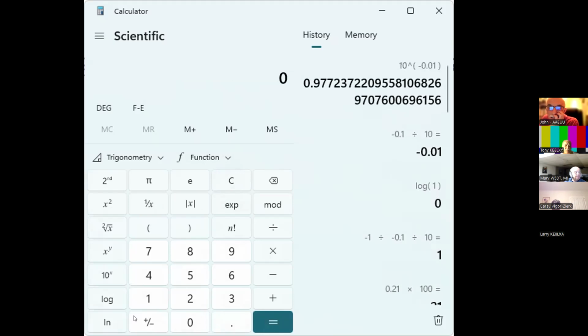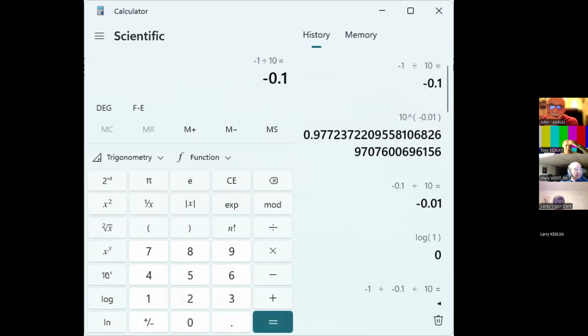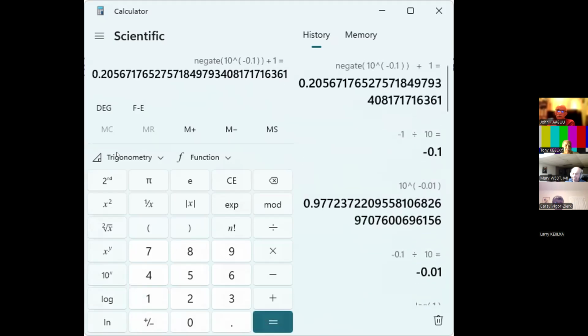1 dB of loss on inverse divided by 10 is 0.1. The inverse log is, there you go, 0.79. Once you got the 79, that's the power through. So the power loss is that much from 1 or plus 1. And there's your answer, the 20%.